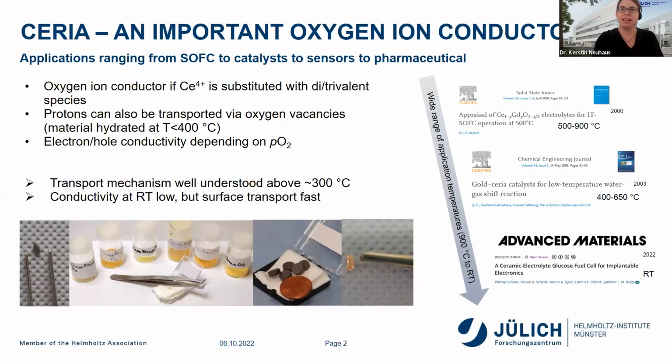cerium dioxide. And ceria actually is a very versatile material after being promoted as material either for solid oxide fuel cell electrolytes or as an electrode constituent in solid oxide fuel cells, because it can have considerable electron conductivity depending on the exact composition, but also oxygen ion conductivity. Recent applications are more and more focusing on the use at temperatures below 300 degrees C. And the material has a high catalytic activity.